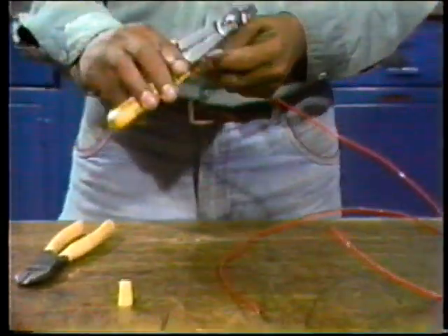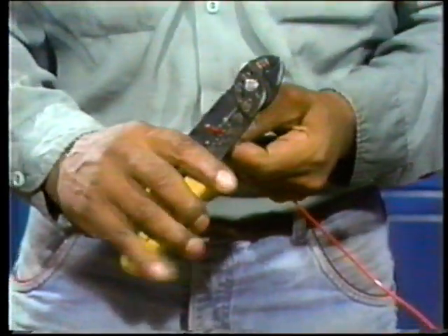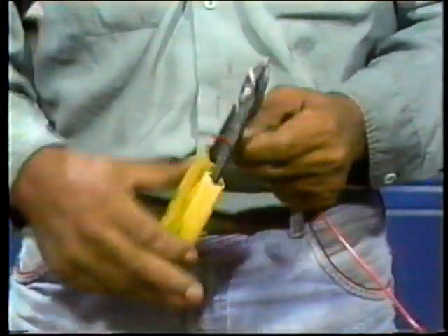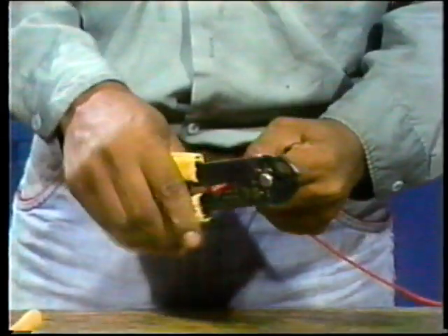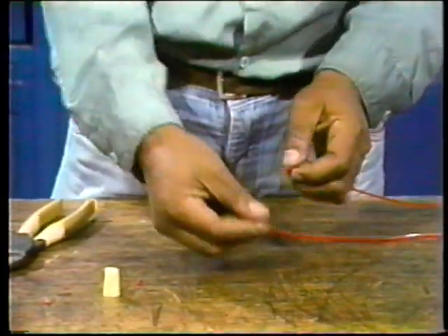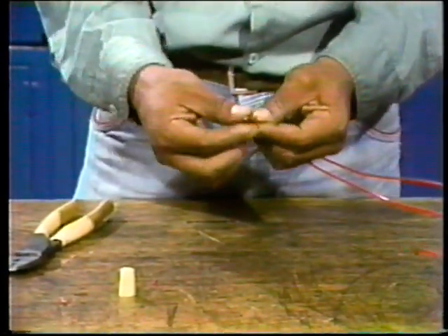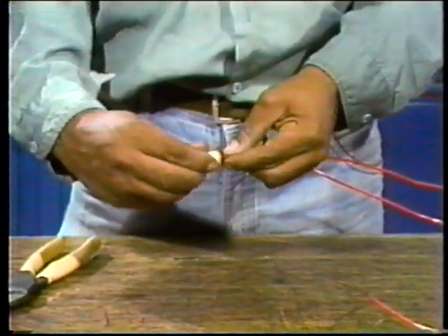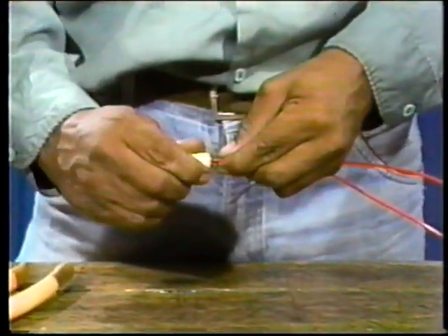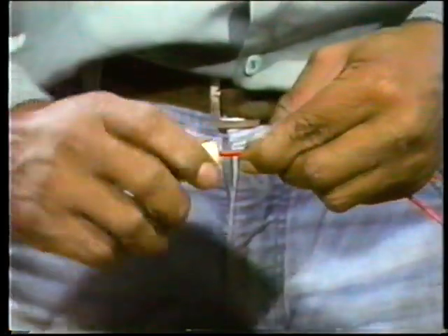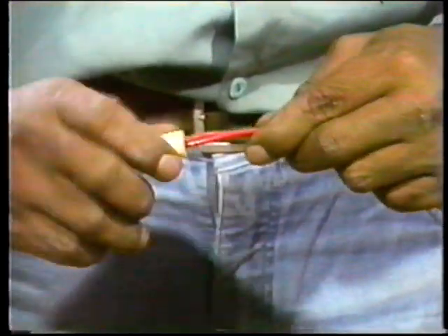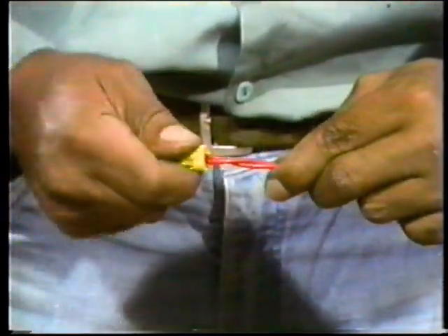Bill's going to use a wire nut to make the first splice. The first step in the procedure is to strip the insulation off the ends of the conductors. He's using a stripper to do this. The amount of insulation he strips off is determined by the size of the wire nut. Now he places the ends of the conductors side by side and slips the wire nut on. He turns the wire nut until he sees the conductors start to twist a little. That tells him that the nut's on good and tight. The wire nut is insulated, so Bill doesn't have to do anything more.